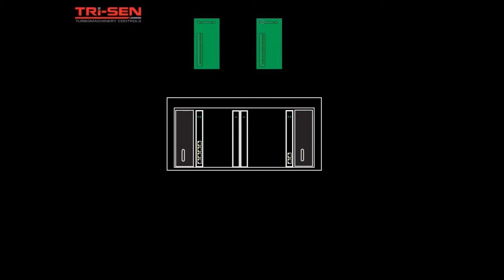Those are multi-core cables that have screw-on connectors on each end. One end goes from the term panel, the other end down to the top of the I/O modules. So there's one cable. We need to add a second cable. And then on the ends of the cables, they have the metal hoods for the mechanical connectors.